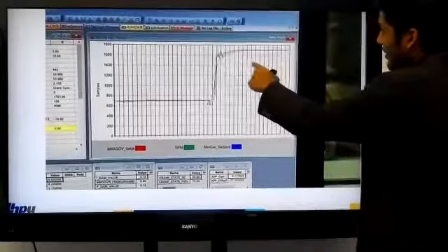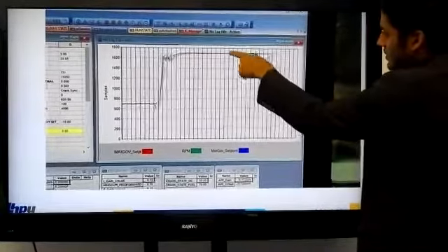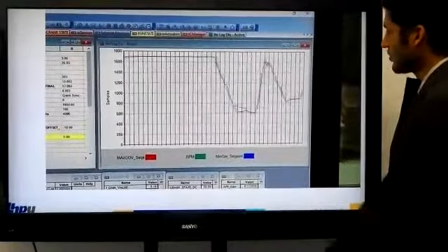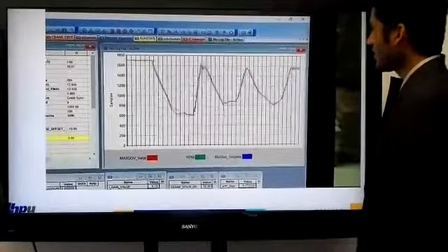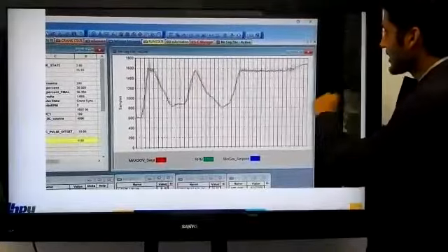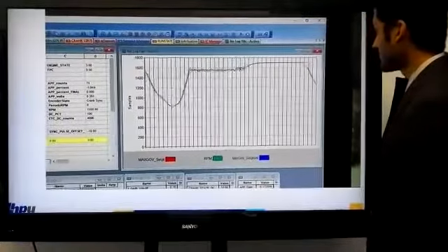And as we gave a full throttle here, we also calibrated the P and I gains for max gov. So that's also running smoothly. We gave varying pedal positions to see how the engine is working. And to my satisfaction, I would say that we did a good job on calibrating the engine controller to make the engine run well.